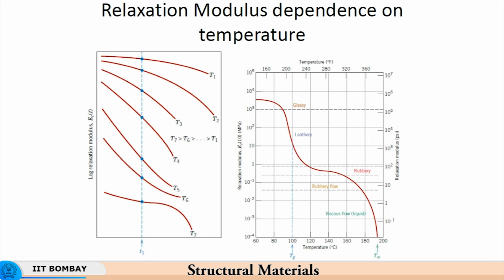Okay, and these polymeric chains, once the van der Waals forces have got weakened, their interactions have two characteristics. One is that of a solid glassy state, and that of viscous liquid flow, and that is the reason why if you apply a certain load, bring the material to a certain strain and leave it with time, there is a time dependent decrease in the load, unlike metal. So this is called as relaxation modulus.